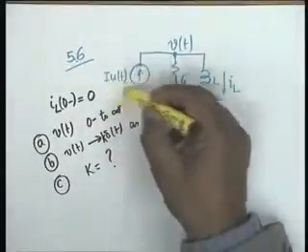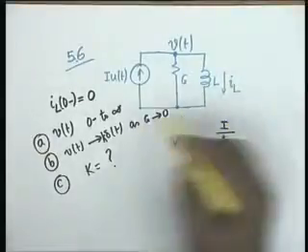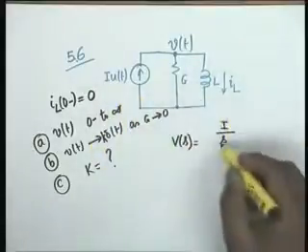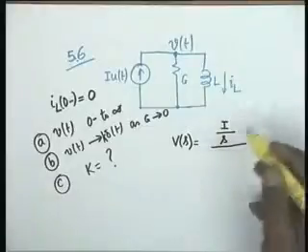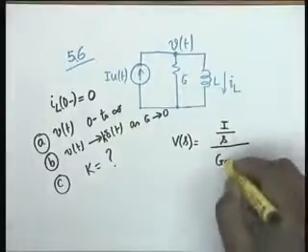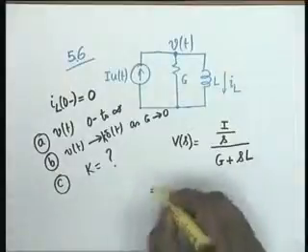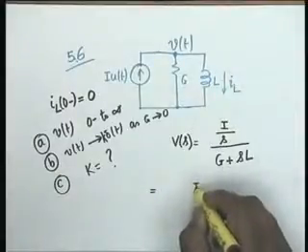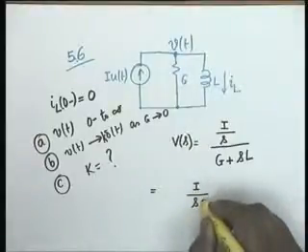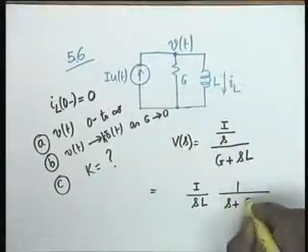The current has a transform I by s, the Laplace transform of I u(t), multiplied by the impedance, which is simply the reciprocal of admittance, and the admittance is for a parallel combination G plus 1 over sL, and therefore V(s) is equal to I divided by s, L, s plus G by L.